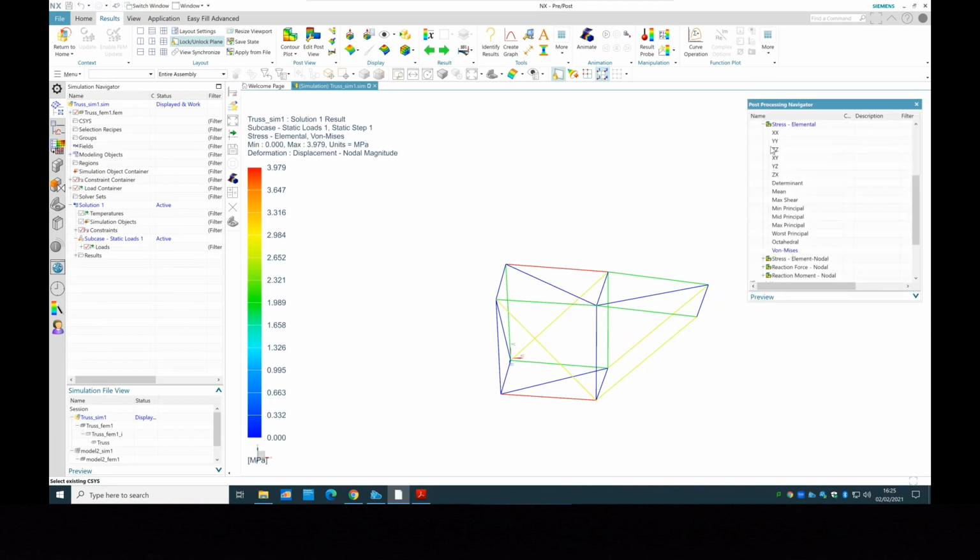And then these stresses, you can do it with two different methods. One is the elemental, one is the nodal. The amount of stress on each element, the elements, those are the lines that you created. The nodes in this case are the same thing. Every element was one node. Do you remember that? But if I said every element is 10 nodes, then the analysis in here, element nodal, is different because it gets the average of every single node. In this case, it's the same thing. But next session, you will see that the results you get are different because every element consists of 10 or 100 nodes, for instance. Go check the von Mises in here as well, and I will play it.